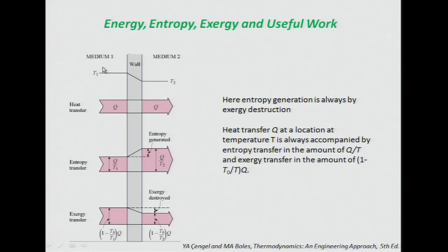So you have a temperature here up at T1. We have a gradient through the wall and a lower temperature here, let's say T2. And in steady state, this gradient, the straight line for a uniform medium, the straight line slope is the solution to the heat equation for constant properties. Then you would just balance the heat fluxes.